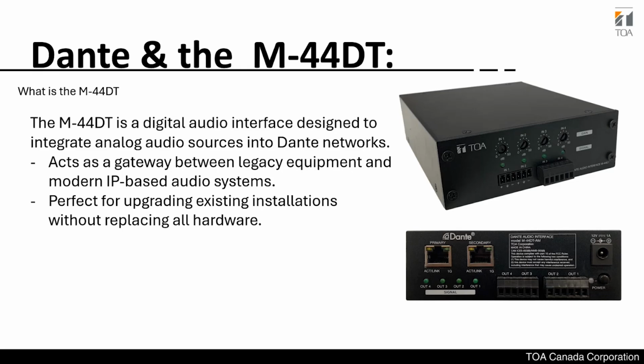So it works as a gateway between old, legacy equipment and modern IP audio, and it is perfect for upgrading an existing installation without replacing all hardware. So how does it work? For example, we have analog microphones, analog amplifiers, analog devices. Instead of running 5 or 6 cables from one location to another, we just put this M44DT, and we can send all the input devices from one location to another.